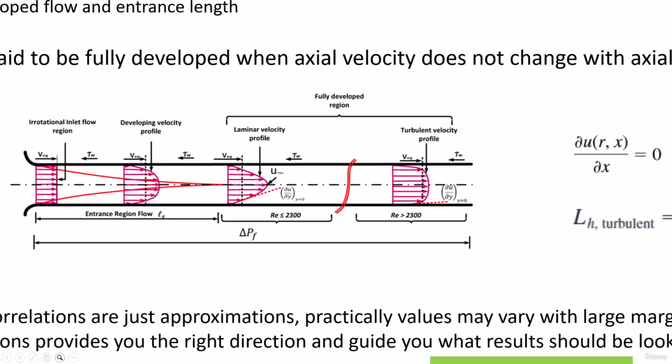That is, if you average this profile by adding all values and dividing by the number of values, it is the same as the inlet velocity at the inlet of the pipe. And in turbulent flow, like Reynolds number greater than 4000, it is surely turbulent flow. But at 2300, the flow starts to change, transitioning. So the flow is starting to change from laminar to turbulent.